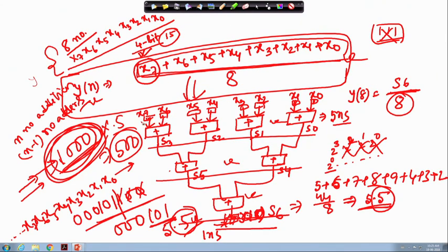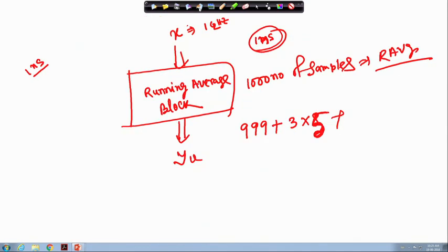And what else is left is the corresponding delay for the input resistors and output resistors. Okay. So, 2 of them I am using. Why 2 of them? I am using 8 at the input side and 1 at the output side, but the 8 are in parallel. Each of these consumes 1 nanosecond delay, so the maximum of that will be the delay for that resistor. So, maximum is 1. I am considering 1 for the input delay and 1 for the output delay.